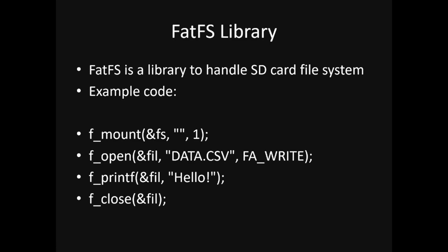And one more thing: after writing to a file, you must close it, otherwise you will not observe anything in the storage. You must close the file and then remove the card. During development I observed many times that if I missed the file close function, then when I connected the SD card, I found zero data written on the card. So you have to close the file. This is the most important thing.